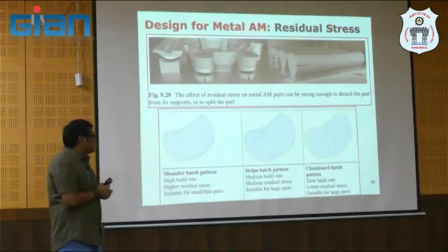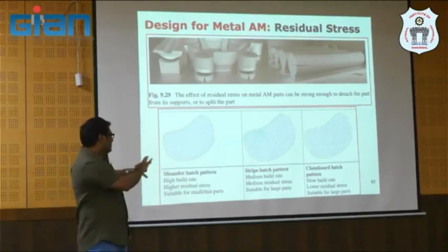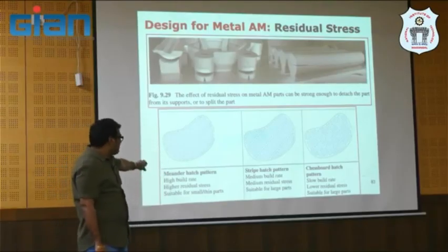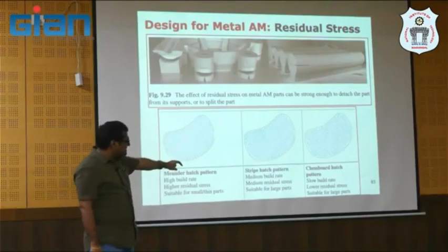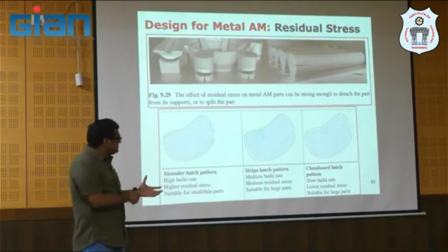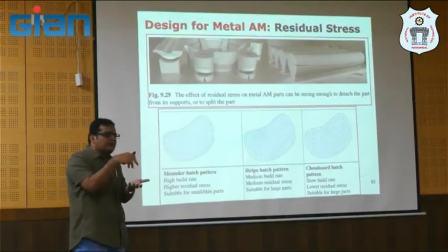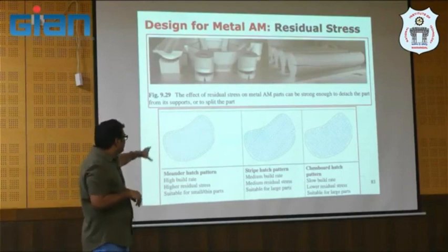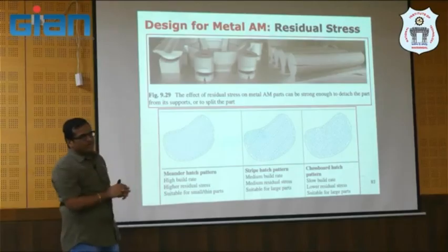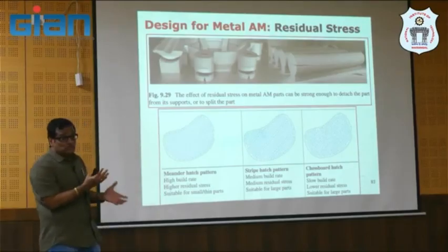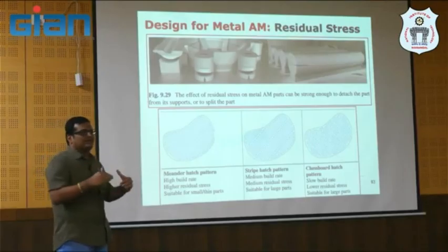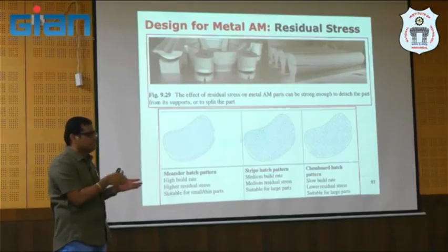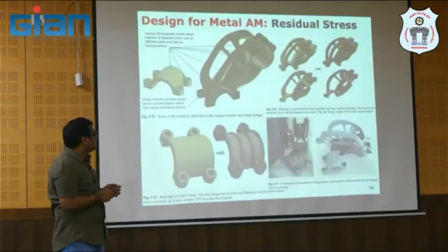Yeah, and the effect of residual stress that we have been talking about, you come out with different scan strategies, maybe with hatch, meander, or maybe stripe, or maybe a chessboard. Why? Because you try to see how the laser interacts with the powder, right? So to some extent we can manipulate, not letting these residual stresses build in a particular region, or you try to vary the scan strategy in such a way that we can reduce these residual stresses.